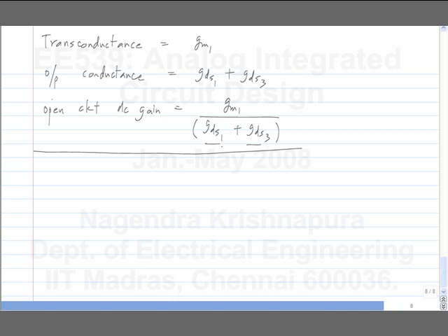Okay, let's say this has to be 100, right? First of all, if you have simulated any inverter at all, you will know that a minimum length device will not do this. A minimum length device will probably give you a gain of 20 or something of the sort in this technology. If you go to more fine line technologies, it will be even smaller than that. I don't know anything else about the technology, so I'll just start with perhaps a length equal to 1 micron in this technology.